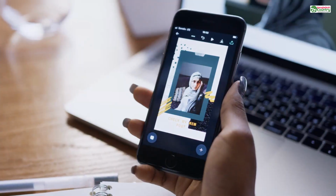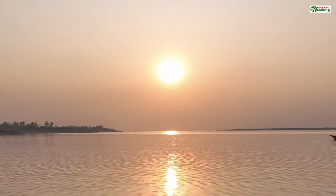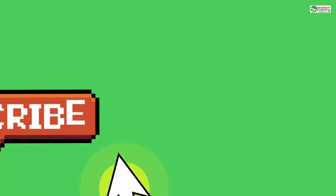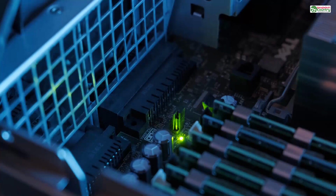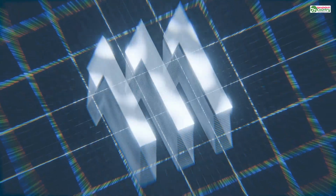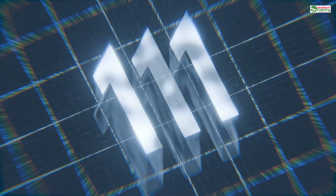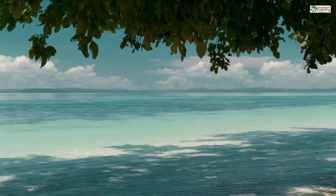You can see instantly that your balloon is leaky. Now for the even better part. Most of these programs have an auto repair function. You click the button, and the software does its absolute best to intelligently patch the holes, delete the internal garbage geometry, and unify the entire mesh into a single, clean, watertight shell. In a huge number of cases, a single click can take a file that was destined for the trash can and make it perfectly printable. It is one of the most satisfying clicks in all of 3D modeling.